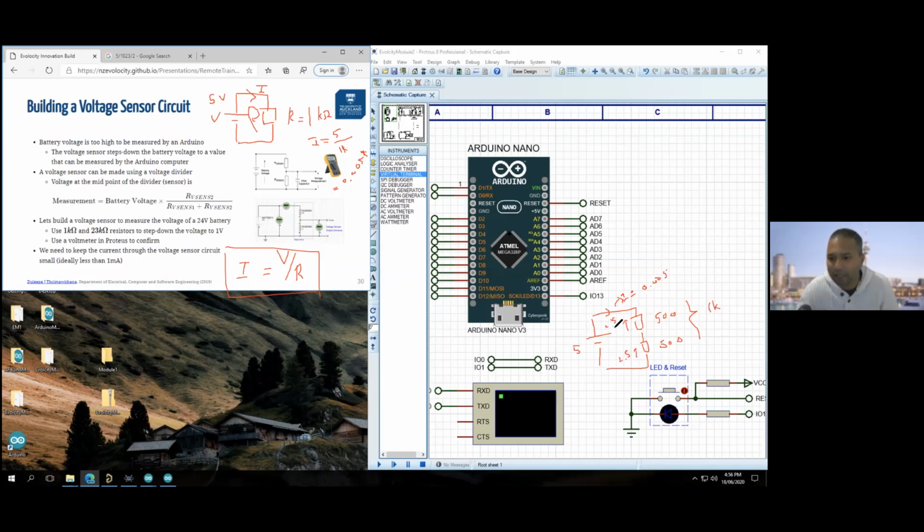Right. Now, if I make this, say, 10 times this resistance, so it will be 5,000 and 5,000. What would happen to this resistance? It will be 10,000, right? What will happen to the current? It would get divided by 10. Another 10. So you have another 0 here. What will happen to the voltage?